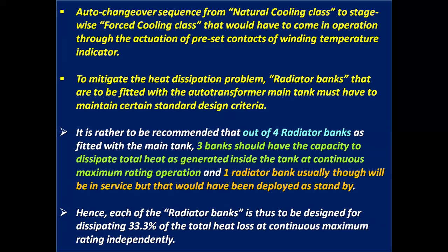It is rather recommended that out of 4 radiator banks fitted with the main tank, 3 banks should have the capability to dissipate total heat as generated inside the tank at continuous maximum rating operation, and one radiator bank, though usually in service, would be deployed as standby.